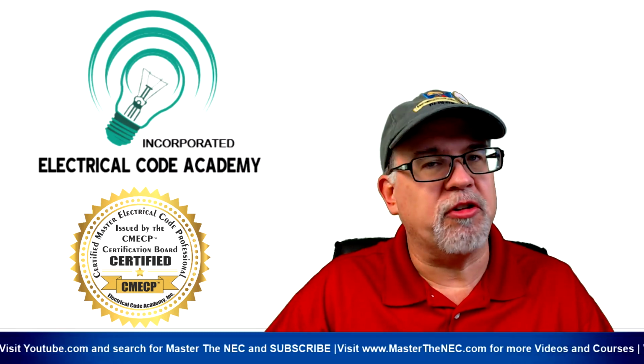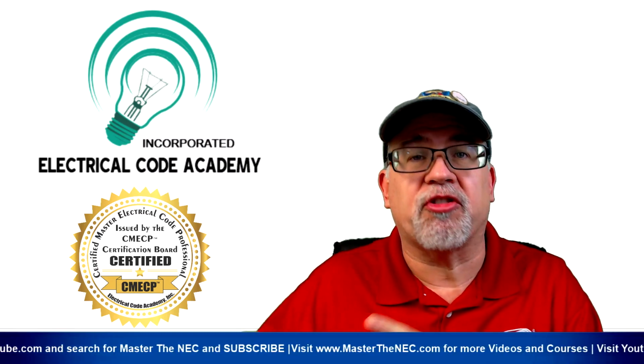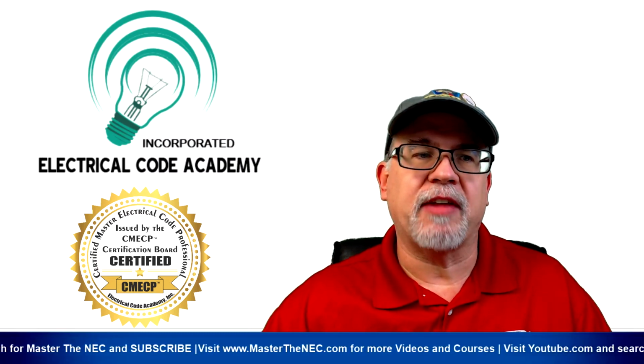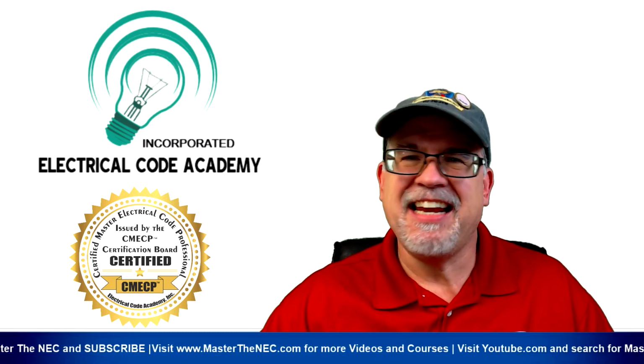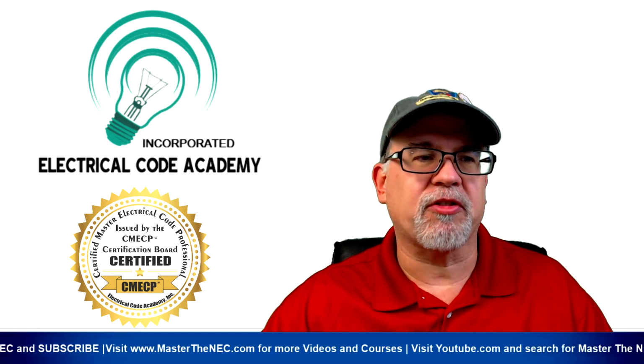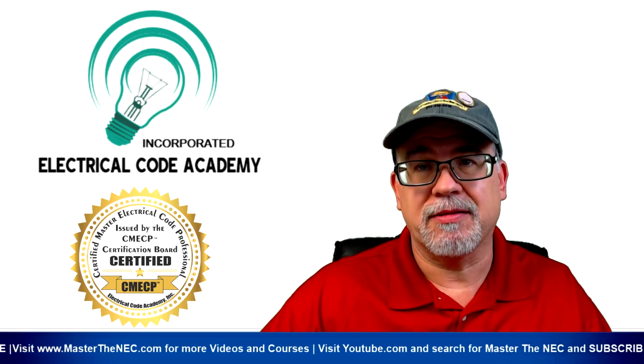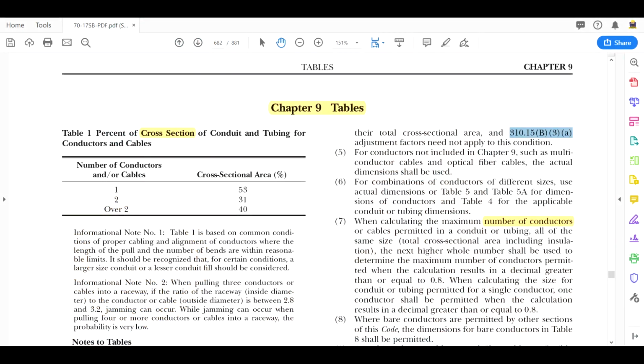Don't forget that. Just because I'm not applying for the current carrying conductors doesn't mean that it might not be a condition where I have elevated ambient temperatures that I have to take into account. Again, heat is not a good thing for conductors when it's trying to increase ampacity or current flow. Okay, it's detrimental. So that's something you want to remember.